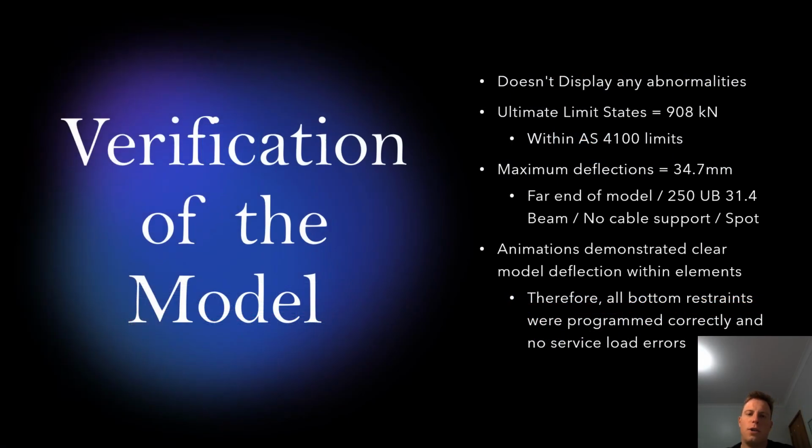The verification of the model identifies that there are no abnormalities occurring throughout its analysis. The largest ULS reading occurs at 908 kilonewtons and the maximum deflection is recorded at 34.7 millimeters. The verification of the model is easily interpreted with the aid of animations throughout Strand 7. These animations qualitatively and quantitatively illustrate the model element deflections, allowing for easy analysis.